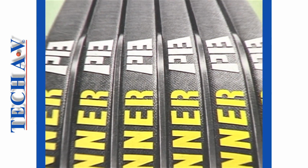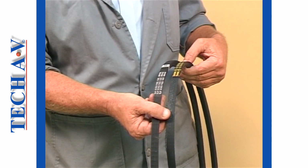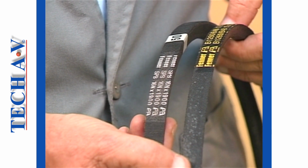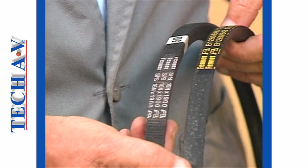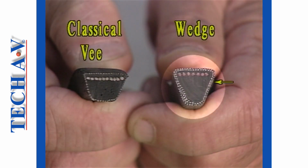We begin this program by first learning to identify two commonly used belt types that you will encounter, namely V-belts and wedge belts. Although at a glance both types look very similar, there are some important differences. Observed in cross-section, the most obvious difference is that a wedge belt has a wider contact face area than the so-called classical V.